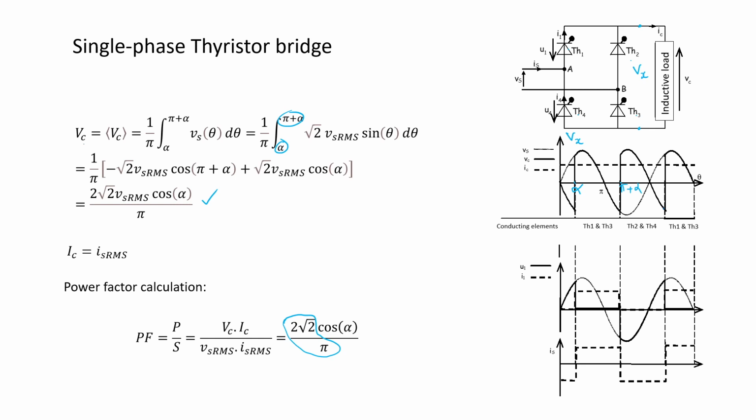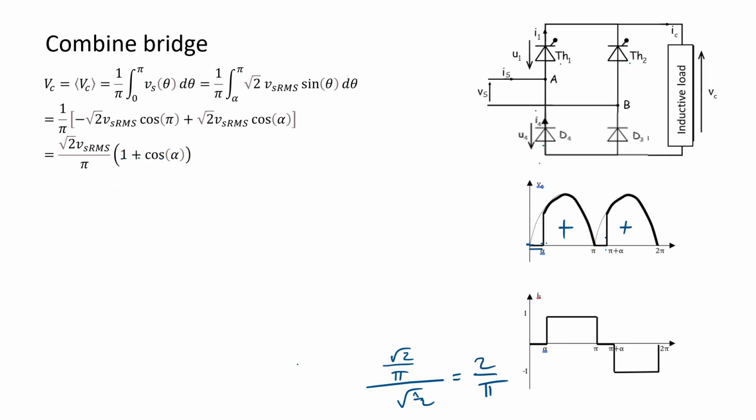Okay. Let's say if DC side has a constant voltage, right? And if you switch this way, it's like you are trying to draw power from the DC to AC. Actually, this is also the initial concept to inverter, because inverter you convert from DC to AC. And the last part of the rectifier is the combined bridge, which means we combine between thyristor and diode.